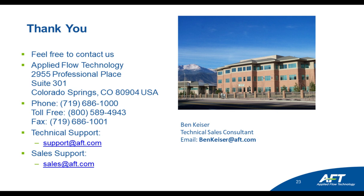So for steady state analysis, you have a bit more flexibility on being able to neglect various parts of your system where you could just put a boundary pressure or flow rate. If you're doing water hammer analysis for surge situations, that's a lot different, because if we are doing an example of a sudden valve closure, that's going to cause a high pressure surge that's then going to reflect and propagate all throughout the system, basically at the speed of sound. And so other areas of your system are going to see those really high pressures as well.